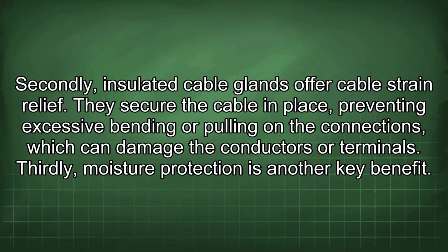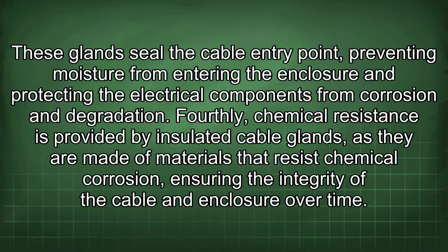They secure the cable in place, preventing excessive bending or pulling on the connections, which can damage the conductors or terminals. Thirdly, moisture protection is another key benefit. These glands seal the cable entry point, preventing moisture from entering the enclosure and protecting the electrical components from corrosion